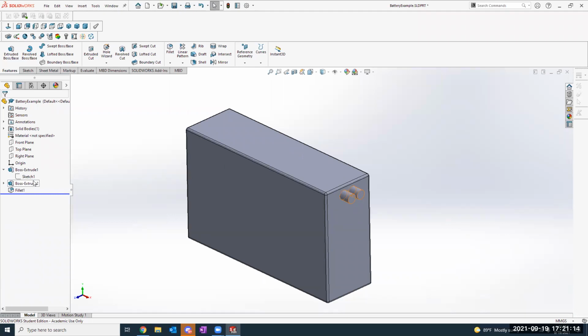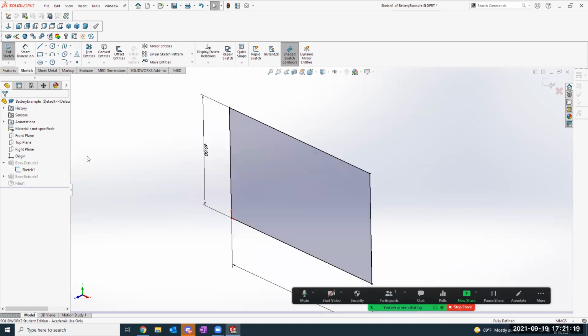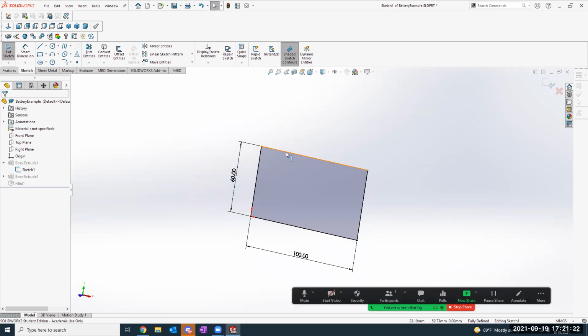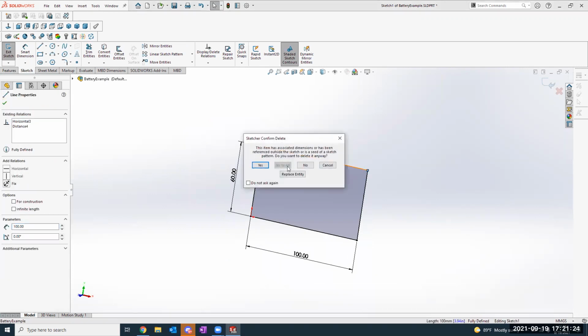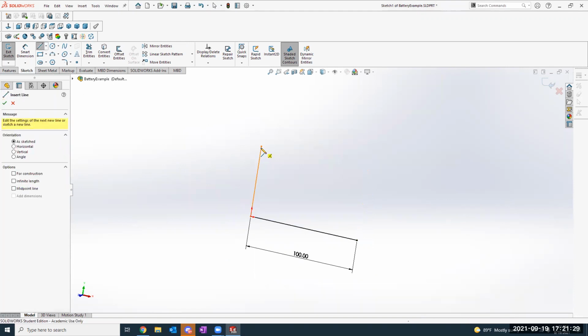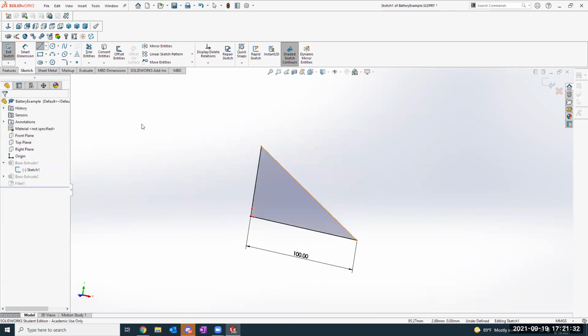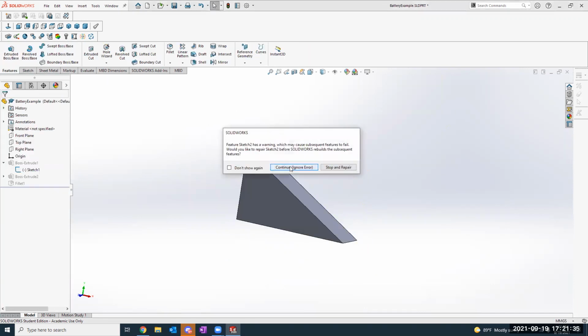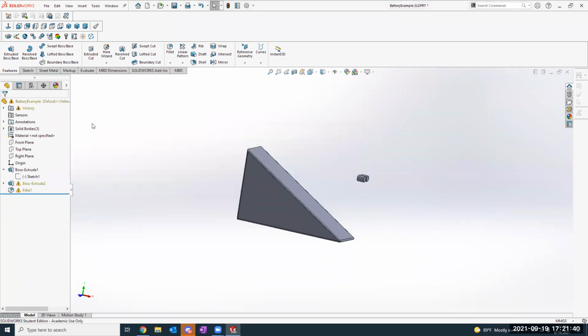Do you have a question? Oh, okay. All right, so let's say I go back to my initial sketch and I screw something up. So let's say I turn this from a rectangle into a triangle. I'll just do something really messy right now. Basically, I've screwed everything up. So I've removed the face that one of our sketches was on before, and now it's going to give me some errors. This is just floating in the air, and this is confused because this face is gone. And the fillet's also confused because it's missing some edges.